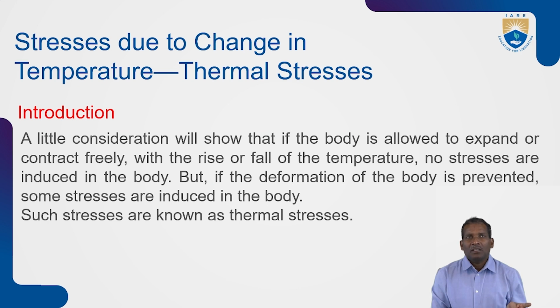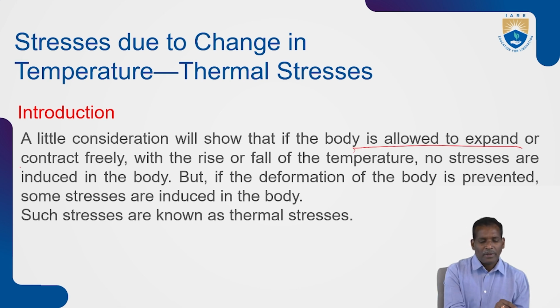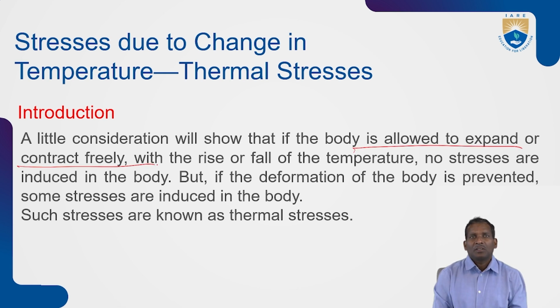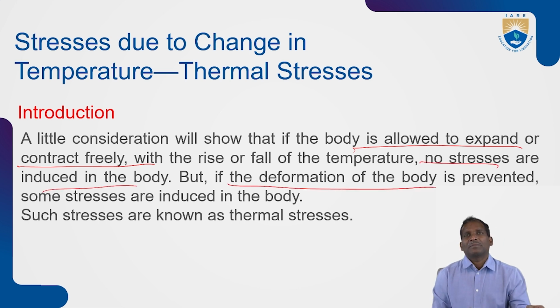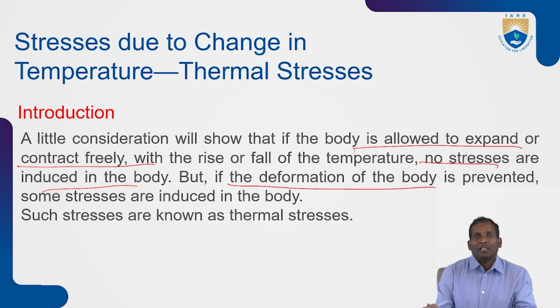Whenever the body is allowed to expand or contract freely with the rise or fall of temperature, no stresses are induced in the body. But if the deformation of the body is prevented, some stresses are induced in the body. Such stresses are known as thermal stresses.